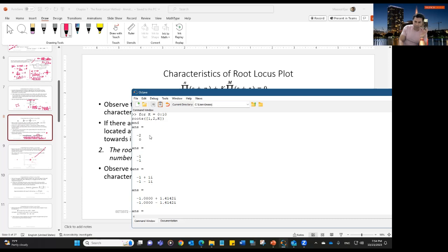If you have, of course, a polynomial that is 5th order, 6th order, you're going to combine all the poles: first poles together, second one, third one, fourth one. On the graph, actually, they will be together anyway. And those will be connected with a line, and those will be part of the root loci.